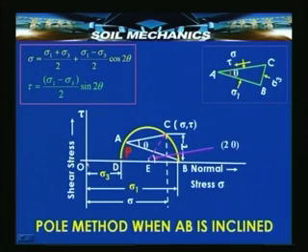Sigma will be now equal to O to this point and tau will be from here to C. And this also is possible to obtain by plotting a line 2 theta through this point E with respect to the horizontal. The corresponding expressions for sigma and tau, which we have already seen, will be satisfied by this point C.